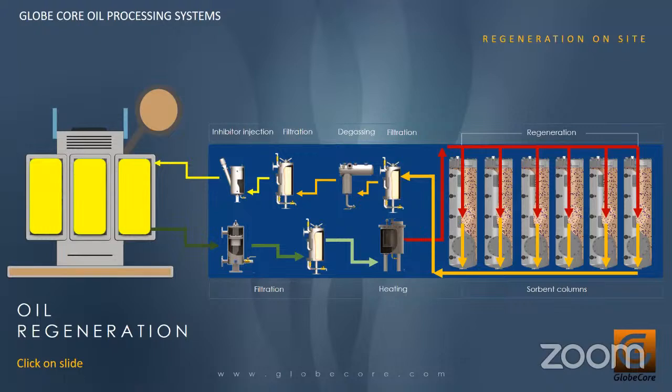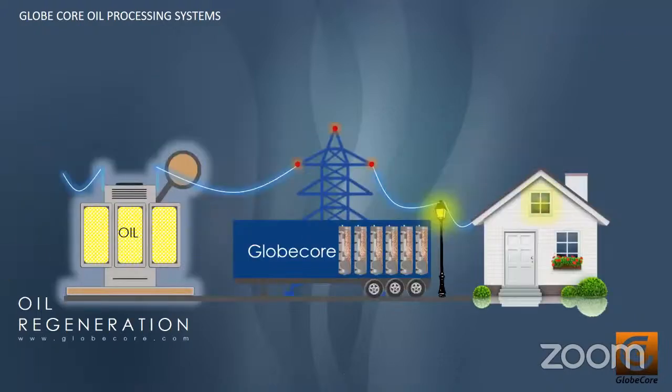Therefore, the passage of oil at a reduced speed can improve the results of the process. So we can say that the quality of regeneration depends on the contact time between the regeneration material and transformer oil. As soon as the Fuller's earth capacity is exhausted, you need to reactivate it, which can be seen on the next slide.